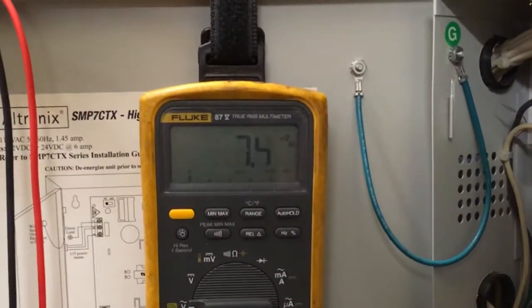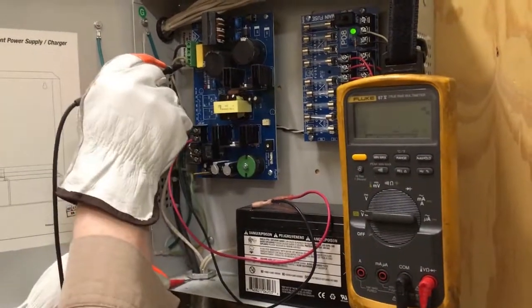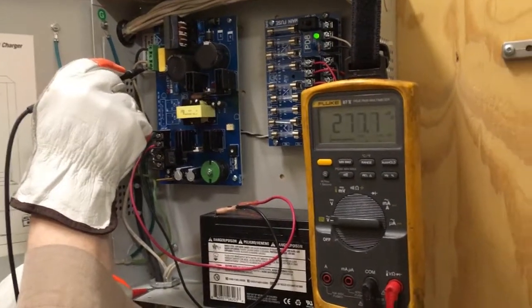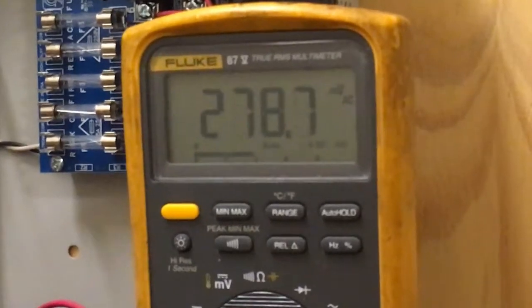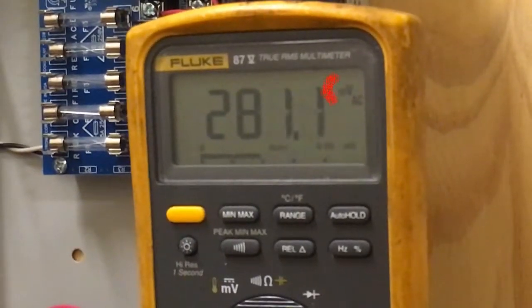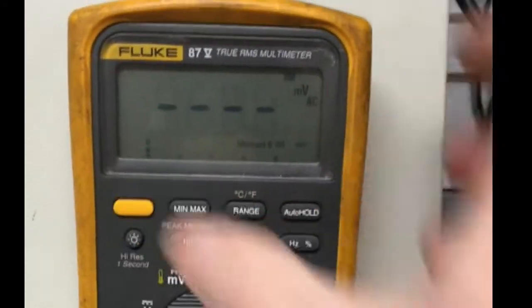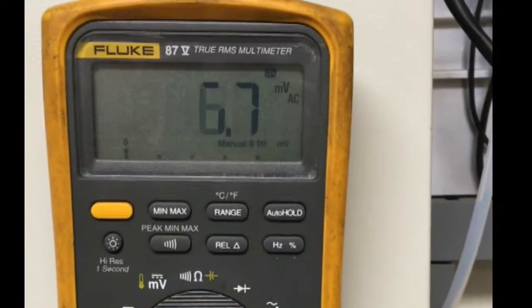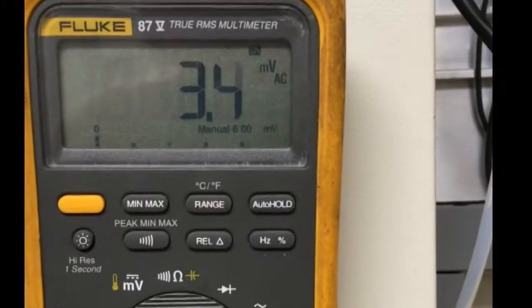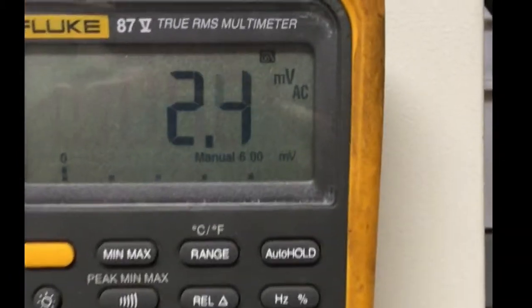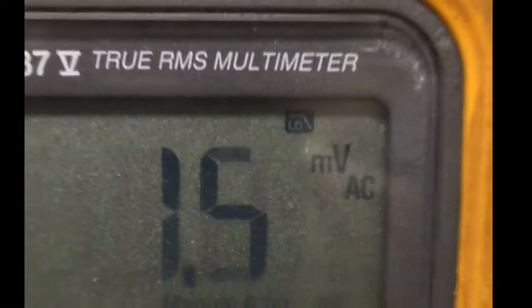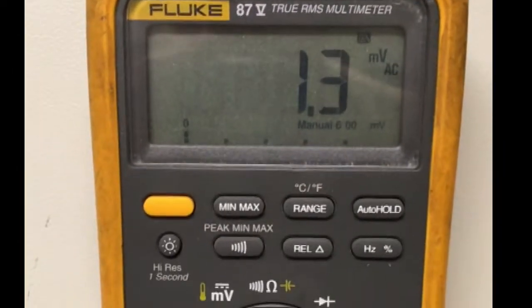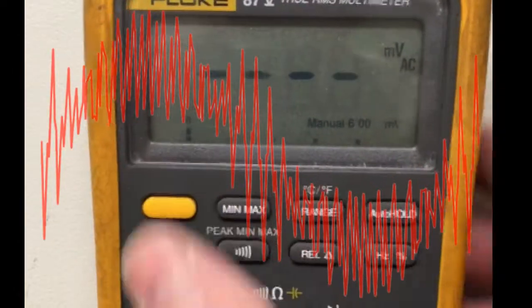Make sure you pay attention to the unit of measure listed to the right of the value. At a quick glance, a circuit that is dead can appear to have voltage, but in fact, the value displayed is in millivolts. If you press the yellow secondary function of the meter while at the AC voltage selection, you will apply a low-pass filter to the measurement. This will disregard higher frequencies. It may be necessary to use this in noisy voltage sources.